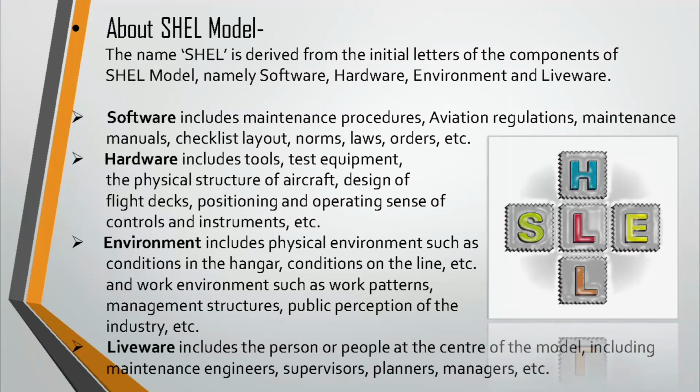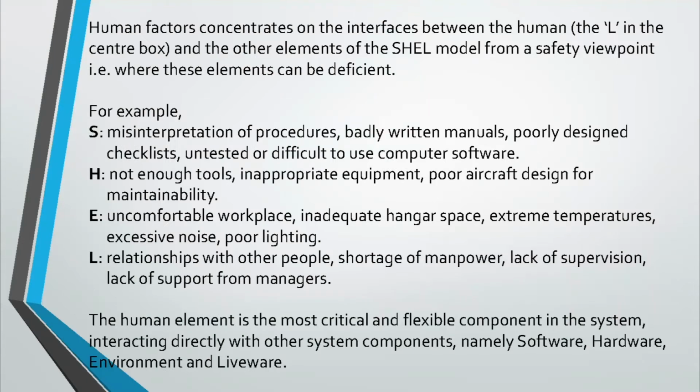Liveware includes humans in the aviation system, whether it is technician, engineer, supervisor or manager. Human factors concentrates on the interaction between the liveware and other components of the SHELL model from a safety viewpoint. That is where they can be deficient, like misinterpretation of procedures, lack of tools, inadequate hangar space, shortage of manpower, etc.